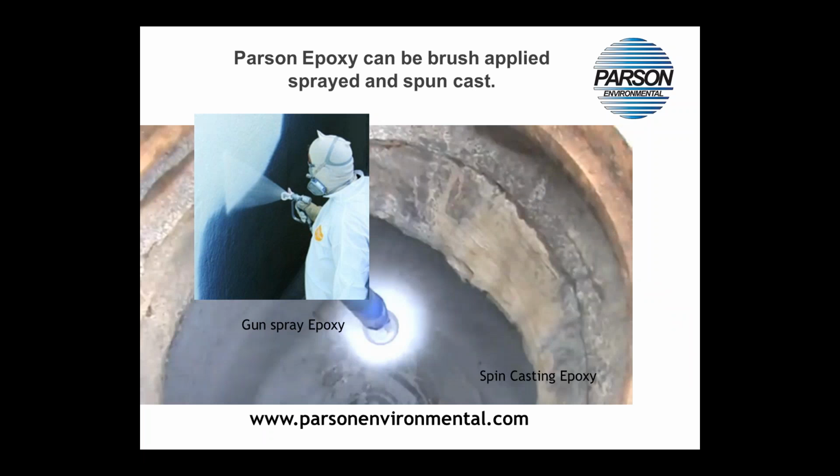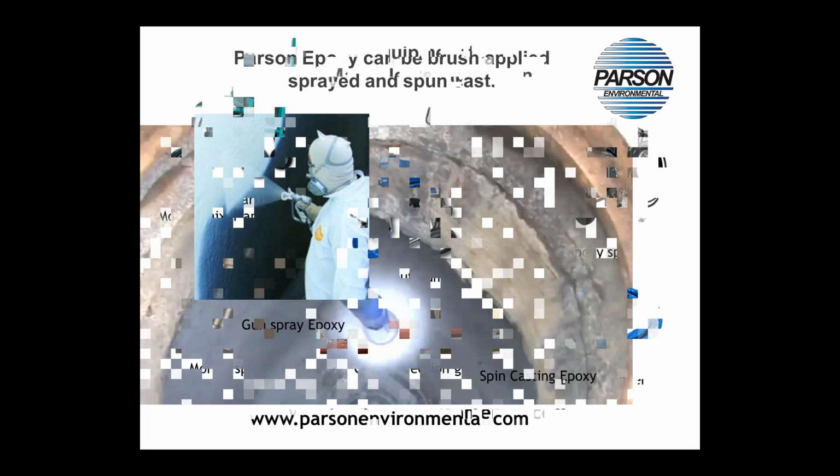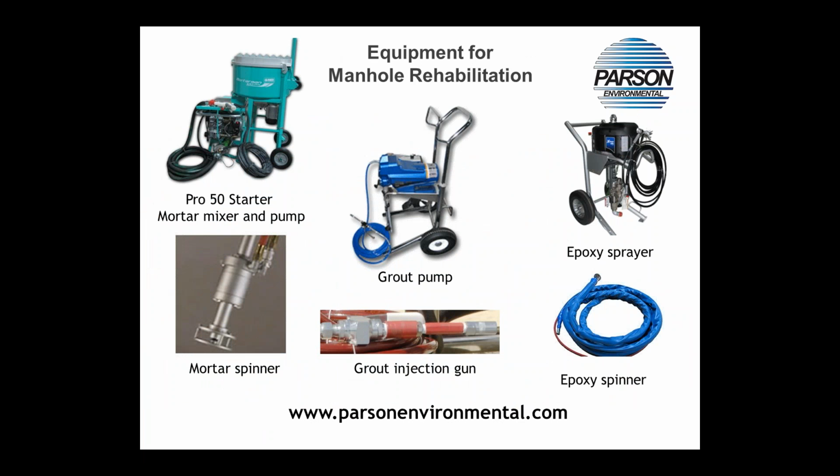Parson provides both a hand-applied and a mechanical chimney seal. The Parson Epoxy FP is a brush-on flexible epoxy urethane hybrid coating that is packaged in pre-measured kits. FlexRib seals are manufactured from EPDM rubber and are installed using 2 stainless steel bands that are locked in place with a specialized installation tool.